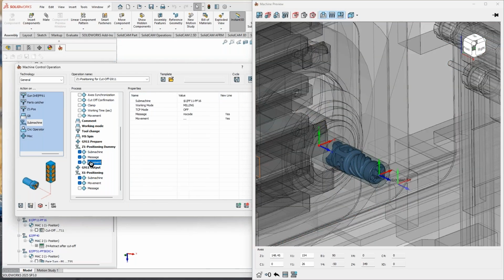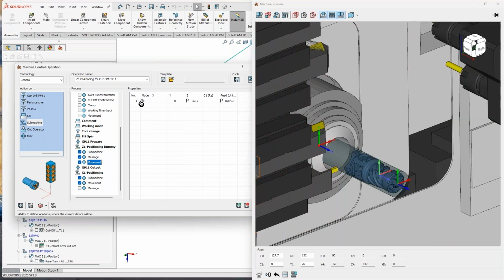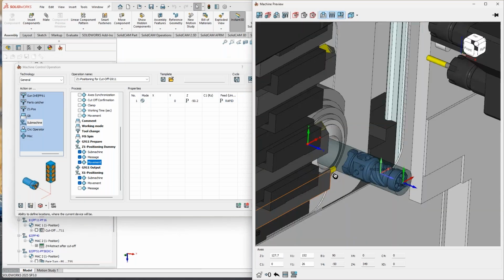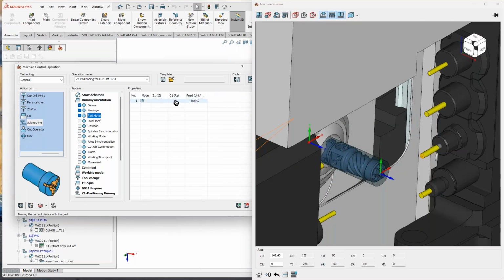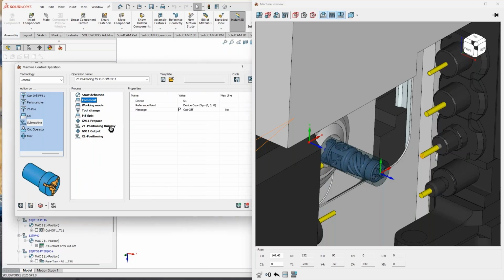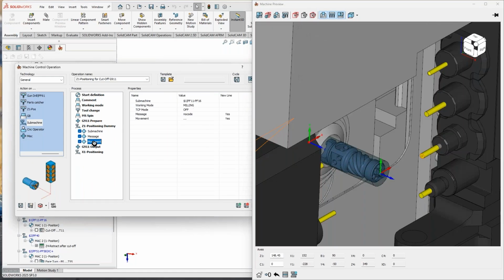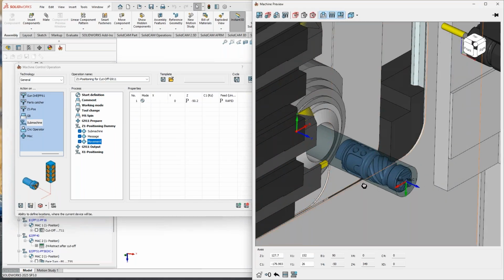The same, we can do over here. If I double click on the mode, it will be the work coordinate system here. And now, regardless of what I'm using here, the part orientation of C or 0, I can just simply remove this. I don't need it anymore. I can go over here and enjoy that every single time my work MAC will be taken into account regarding what submachine has actually been used on the machine.